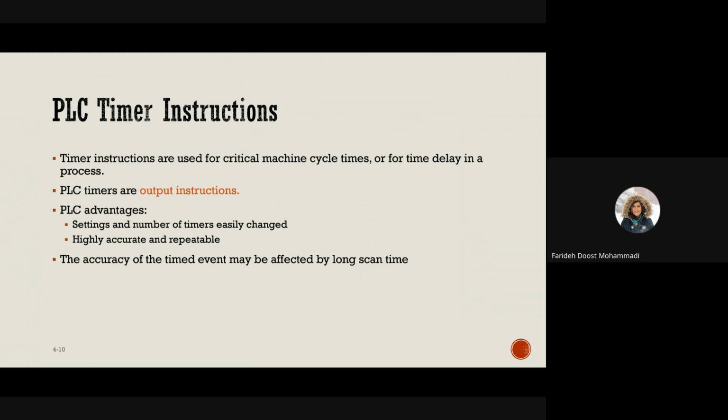So you have to make sure that in very long applications, you are using a physical timer. We're going to talk about it later, that in each PLC there is an actual physical timer that you have access to, and that timer independently calculates the delay.